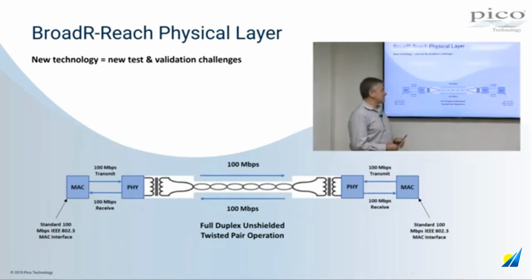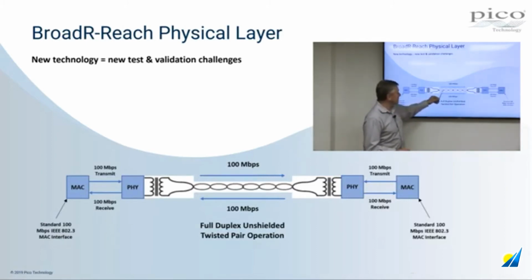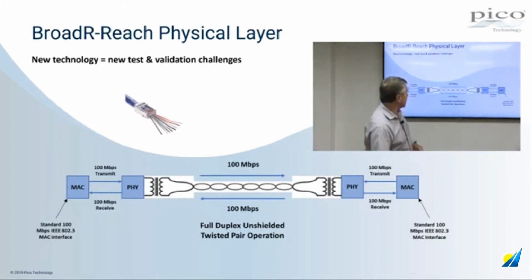So in fact this is kind of how the communications network looks between two transceivers. For instance, a master on the left and a slave on the right. The section over here would be traditional Ethernet hardware on both sides, but the PHY, the physical layer implementation of BroadR-Reach, takes us to a world where we have just a two-wire twisted pair that's transmitting the information of the Ethernet.